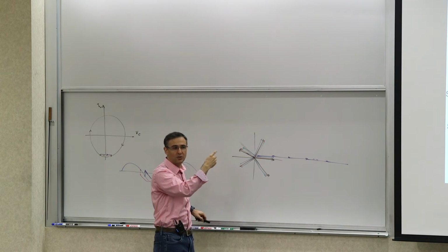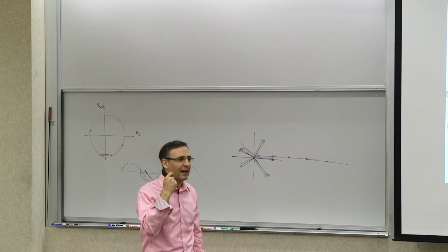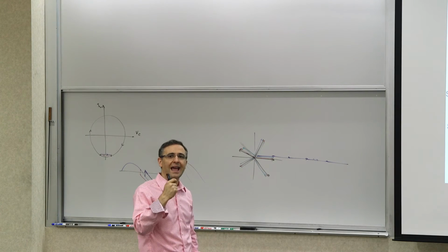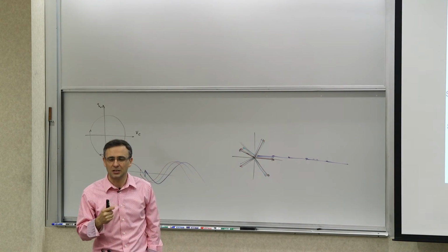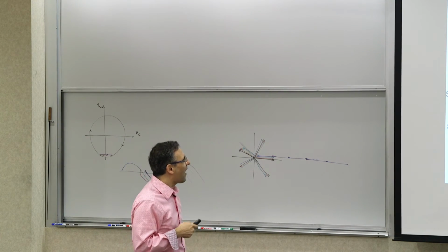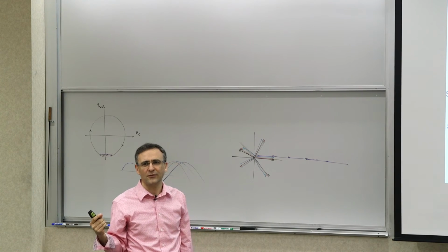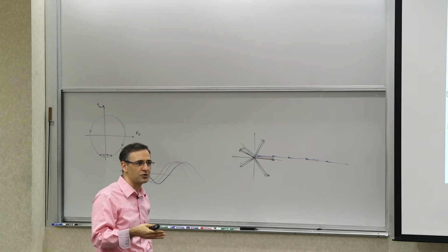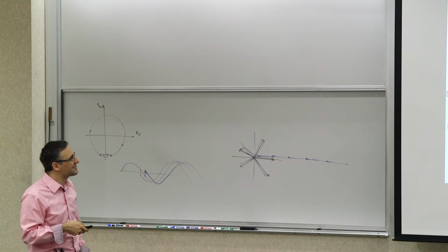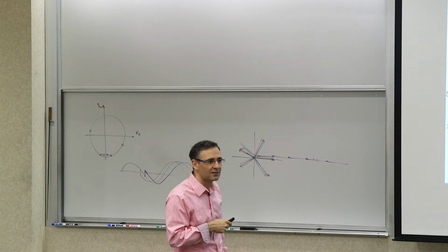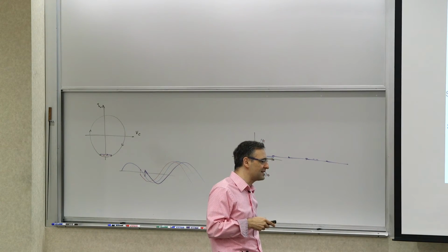DC, of course, has no phase, so they all add. So if they are fully correlated, it's only the nth harmonic, where n is the number of stages, that matters, including 0. So ISF usually, if you have a 5-stage ring oscillator, by the time you get to the fifth harmonic, it's not that large. So you can try to minimize it. But the part that's really left is the DC part. So the DC part is going to stay. So the sum can be approximated as the DC part.